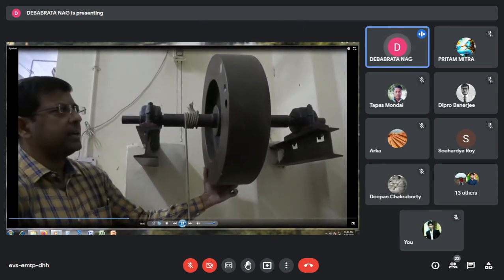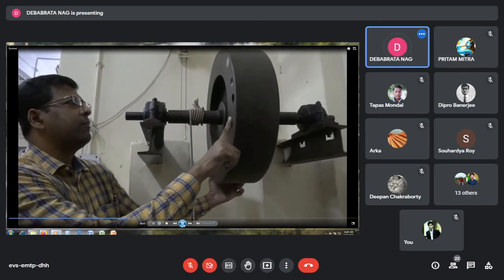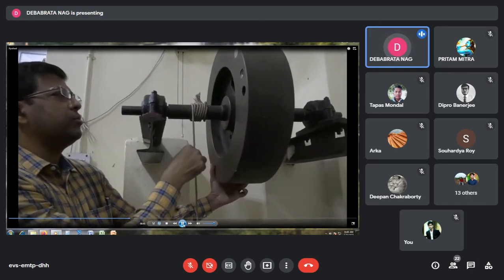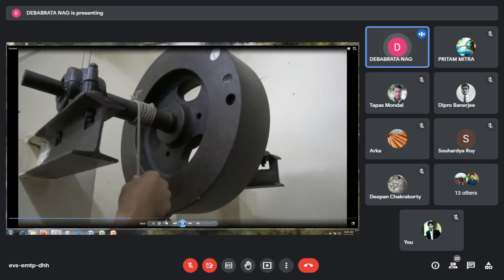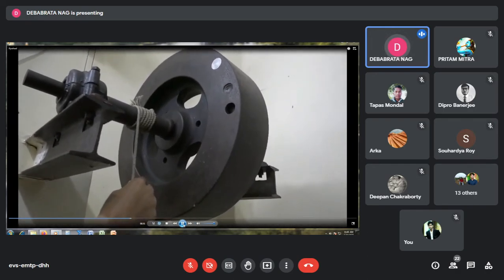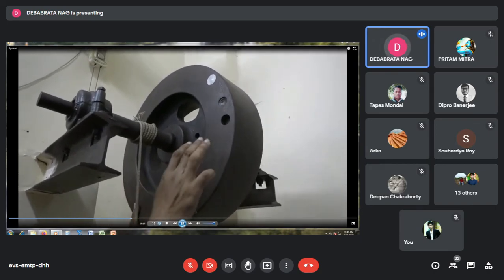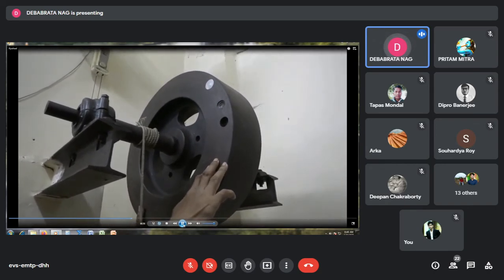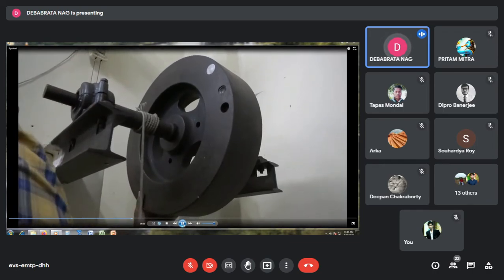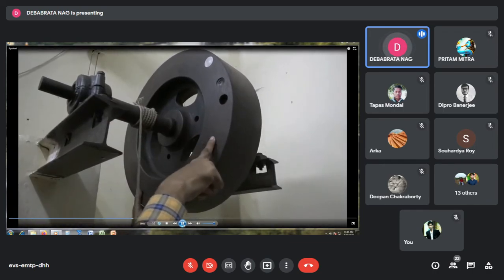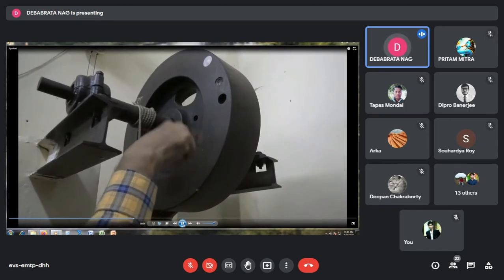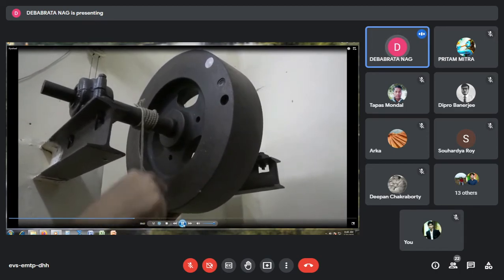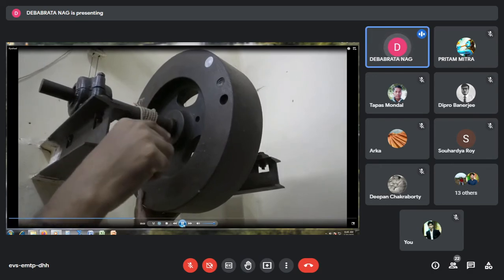The moment it hits the ground, the flywheel starts retarding because there is no more driving torque. The wire tension becomes 0, so the driving torque becomes 0. The only torque acting on the system is now the retarding torque due to friction across the bearing. So after reaching maximum speed, its velocity starts decreasing, and slowly it comes to a stop.